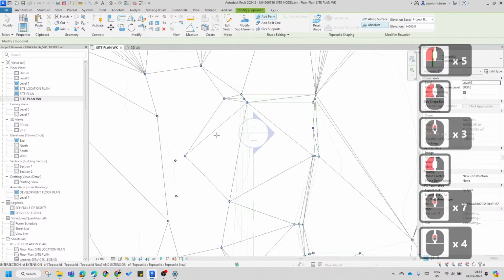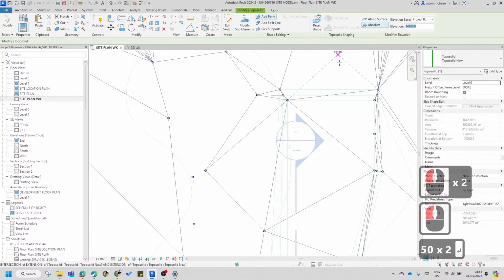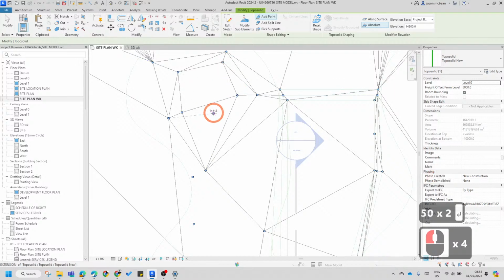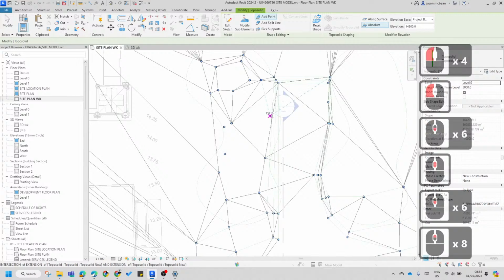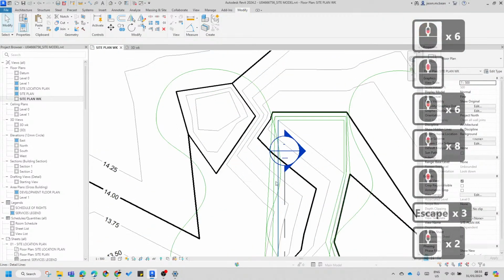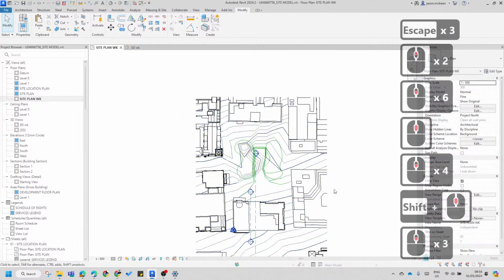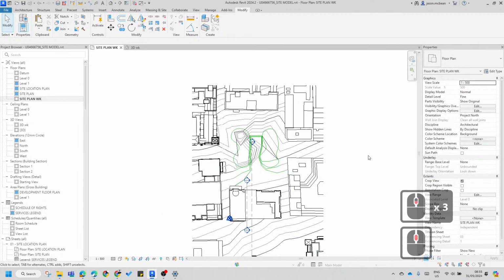Let's create a high point here. Then you can go and make that a little higher in the middle again. So 1500, 500, so 1450. Put one there, put one there, put one there. That's made a little high spot there. Okay, it looks strange, but every time you exit, you'll notice now how that's changed quite dramatically. Okay, but remember you've got the old surface every time to go back to. Yes. So you can copy it again.